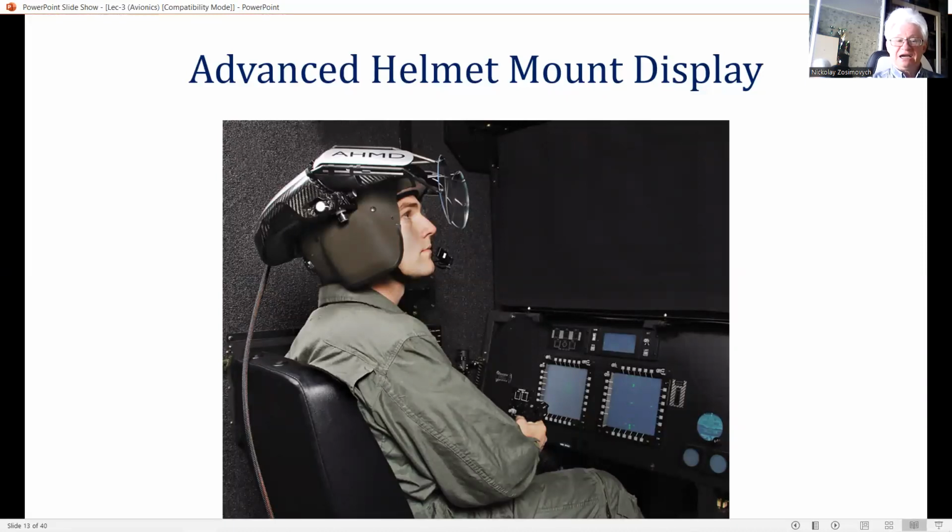A typical seeker head needs to be pointed to within about 2 degrees of the target to achieve automatic lock-on. Missile lock-on is displayed to the pilot on the HMS, and an audio signal is also given. The pilot can then launch the missile. This enables attacks to be carried out at large off-boresight angles, giving agile missiles with high G maneuvering capability.